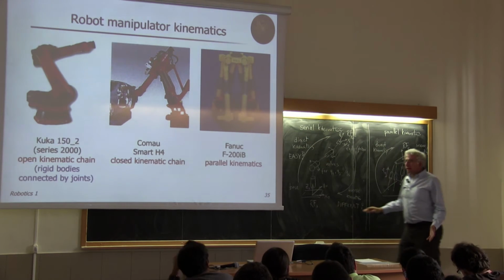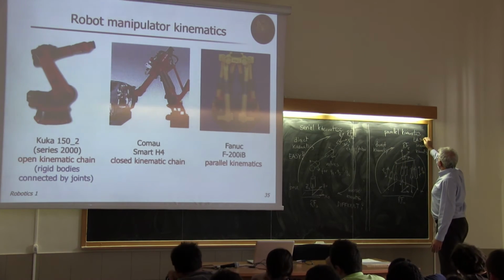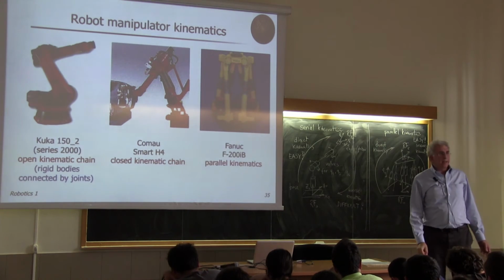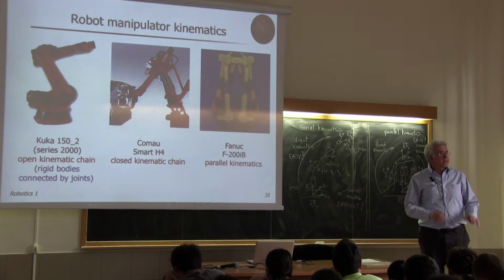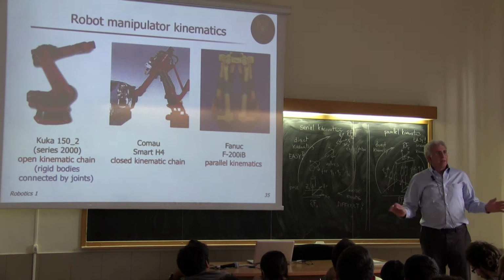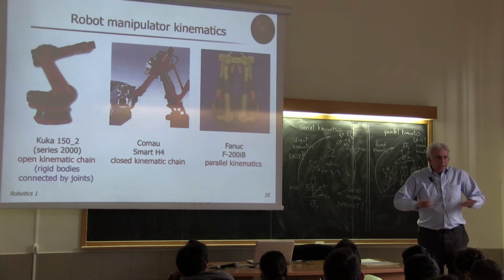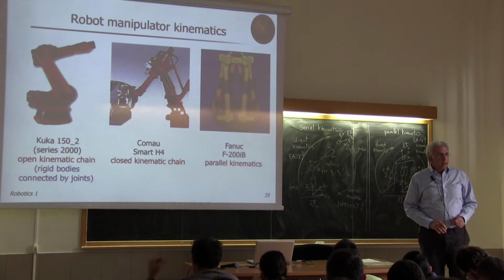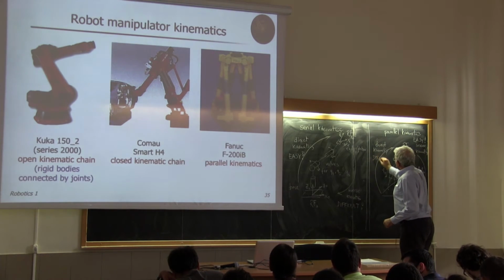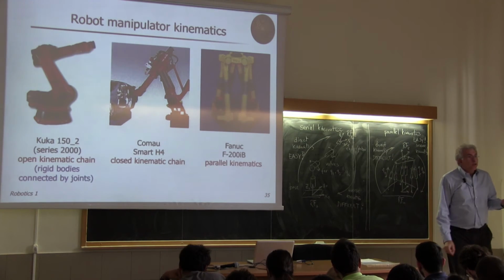The intriguing thing is that inverse kinematics is easy. And in fact, we can find a closed form solution quite easily. Because the problem is of the type divide and conquer. So we can separate the problem of finding the values of the joint variable Q1 to Q6 in independent problems. While the direct kinematic is difficult. Sometimes it has no solution.